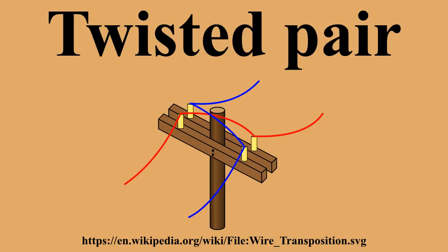When nearby pairs have equal twist rates, the same conductors of the different pairs may repeatedly lie next to each other, partially undoing the benefits of differential mode. For this reason, it is commonly specified that, at least for cables containing small numbers of pairs, the twist rates must differ. In contrast to shielded, a foil twisted pair, unshielded twisted pair (UTP) cable is not surrounded by any shielding. UTP is the primary wire type for telephone usage and is very common for computer networking, especially as patch cables or temporary network connections due to the high flexibility of the cables.